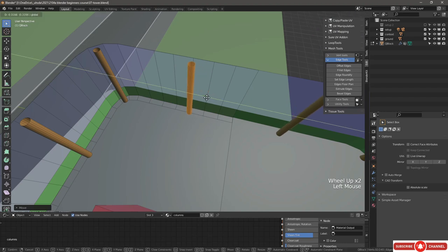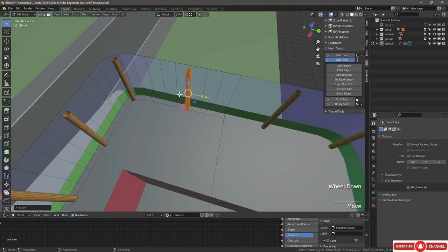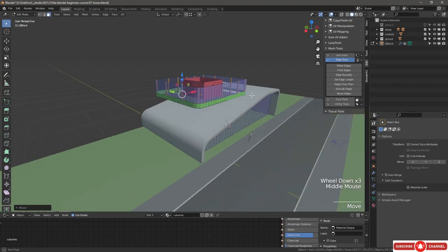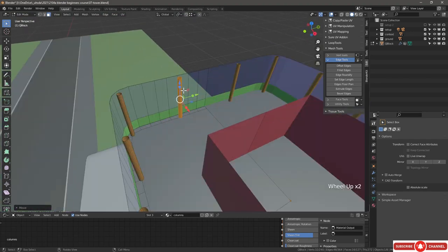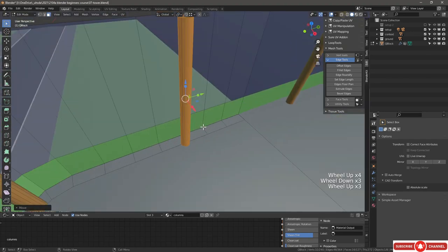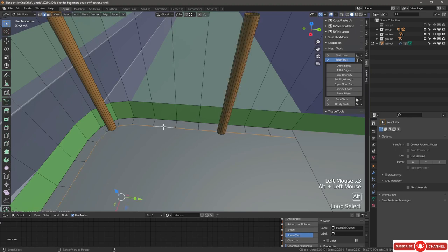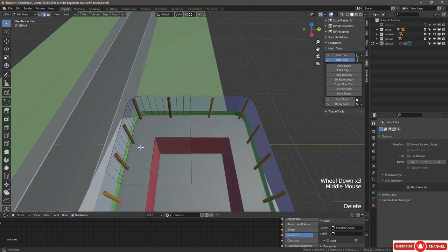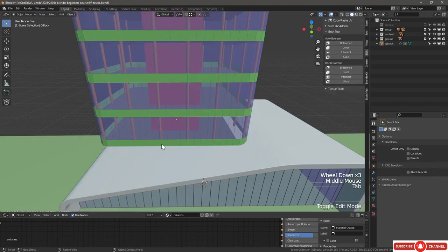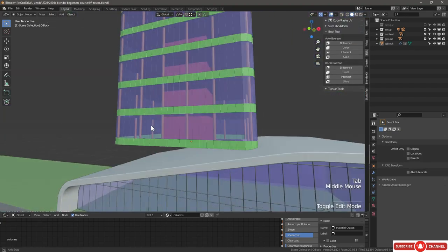Now, in this case, it might be slightly different because I prefer aesthetically for the facade to be aligned to the curtain wall. The columns to be aligned to the curtain wall, or the other way around, the curtain wall to be aligned to the columns. Let's go into edge selection, and then Alt click, and then X vertices to delete that helper grid that we created for ourselves. So that's what our building looks like right now.